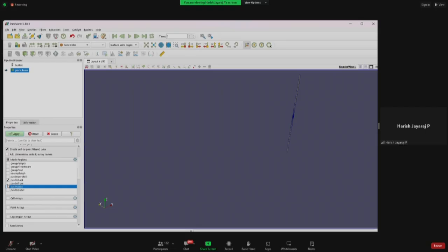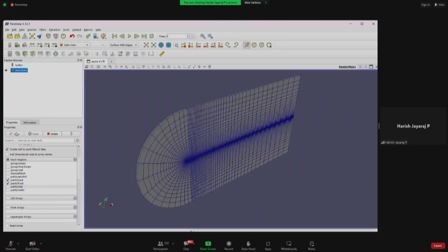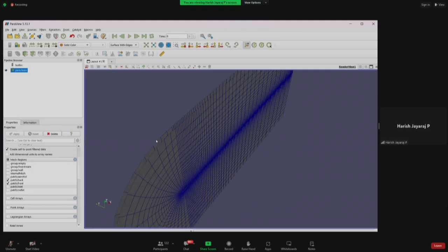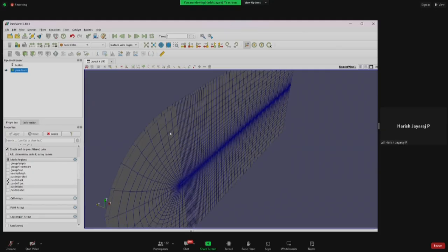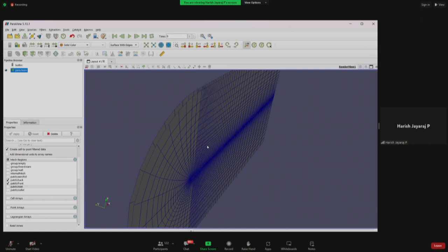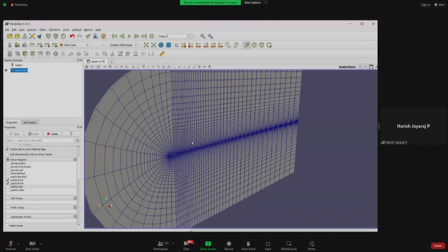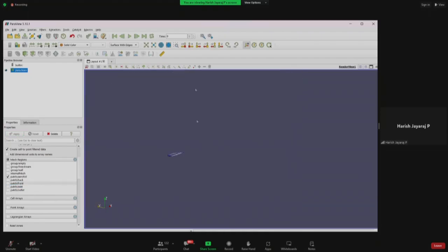And as we were explaining how OpenFOAM takes only 3D and not 2D, you can see that there are two planes here, the front and the back. So these two are defined as empty so that the mesh actually behaves 2D, which we will explore further while we are exploring the boundary conditions. Now, the major thing which we are interested in is the body, the airfoil. So this is the airfoil which we will be working with.